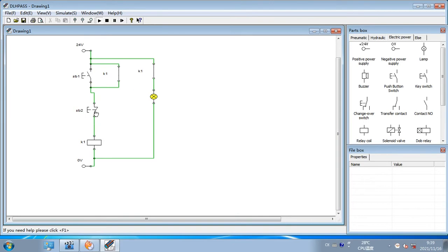And then you press this button right here. You can see when you press this button, it turns on. So this is the on button, and right here this normal close button, when you press this it goes off. So you can see this is a 2-button operation to control a lamp using a relay. When you press it, it turns on. When you press this, it goes off. And let's go to the next section, next practice.